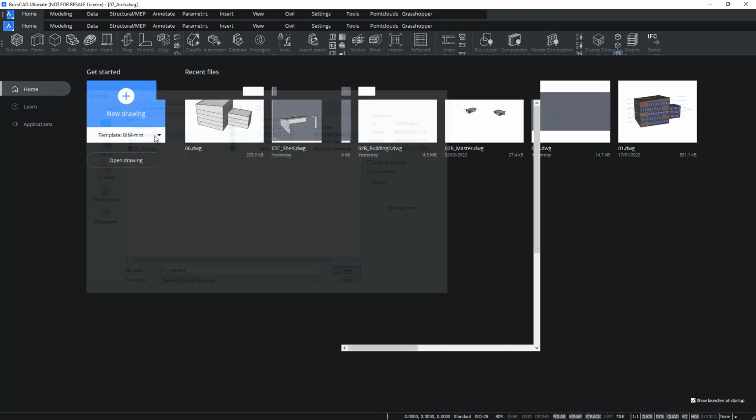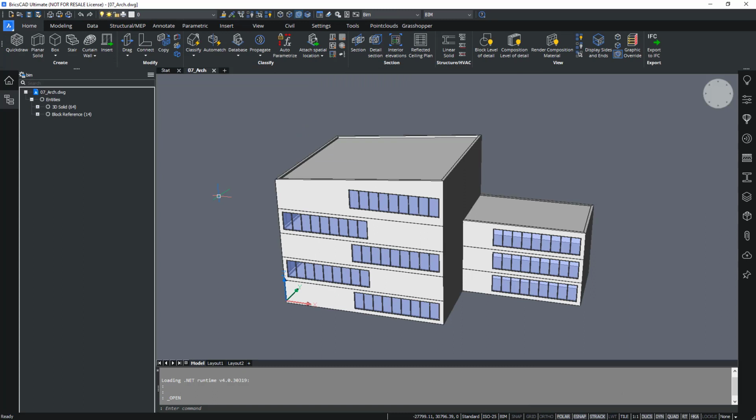We open the architectural model, and we will see in the structure panel that's now active in the BIM configuration that actually we just have solids and block references, so we don't have any BIM data yet. How does the structure browser work? As briefly explained in a previous section, the tree structure of the structure panel represents a hierarchical set of rules